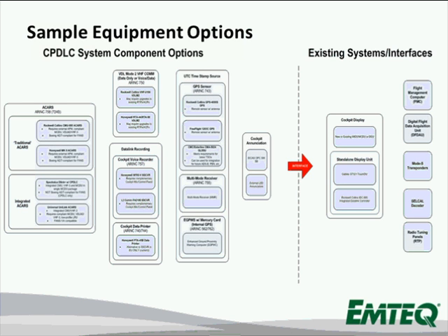We show the options for the UTC time stamp source: the GPS sensor, the multi-mode receiver, or the eGPWS with a Mercury card. There are several independent sensors which can be used. Most of the MMRs are typically service bulletin upgrades, or come from the manufacturer already installed when the aircraft is delivered. For the cockpit annunciation, we mentioned either using an ICAS software service bulletin or external LED annunciators. And what we're showing on the other side is just some of the systems that the CPDLC system requires.